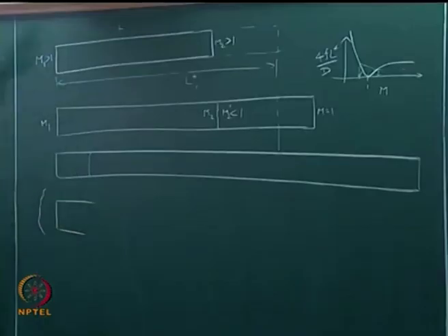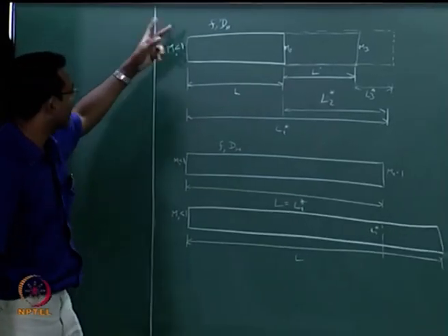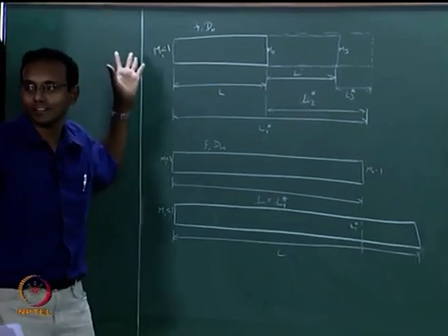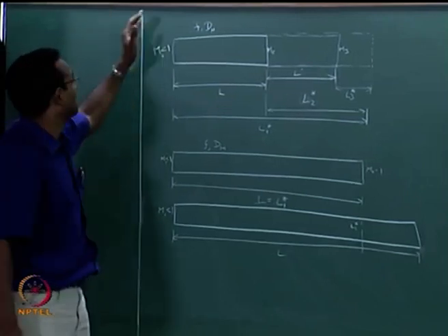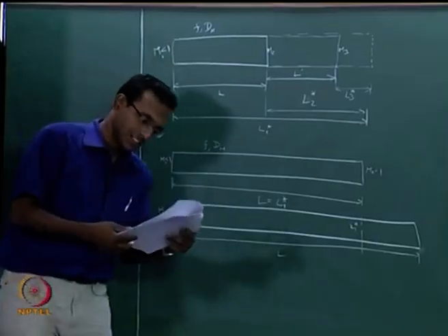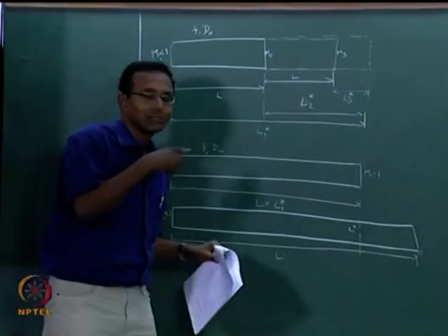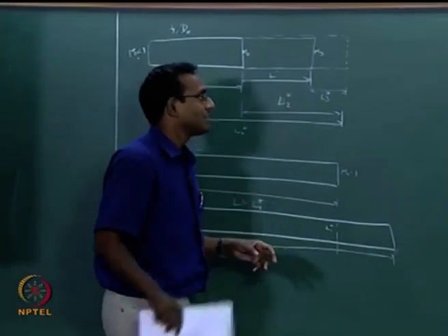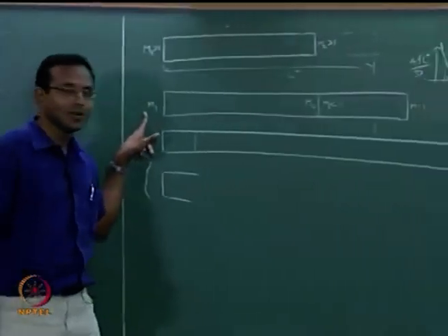I will go back to the other board here and the problem just becomes this. Of course, there may be a shock sitting in front of it, and before that there could be supersonic flow even here. I am not showing you that part here. With this idea, I just wanted to reiterate this whole thing in one sequence. What if I start with M equal to 1 in here, M1 equal to 1?